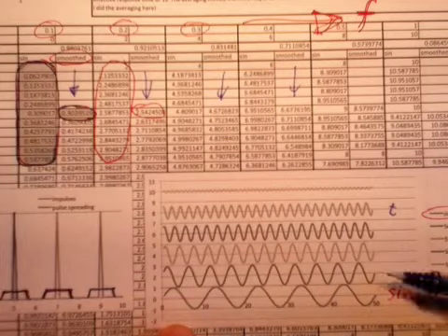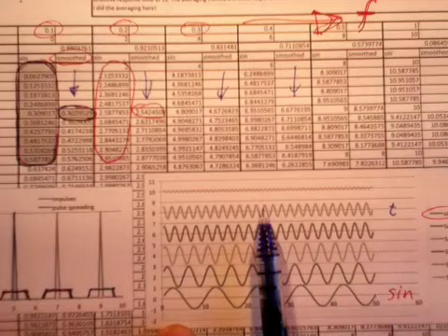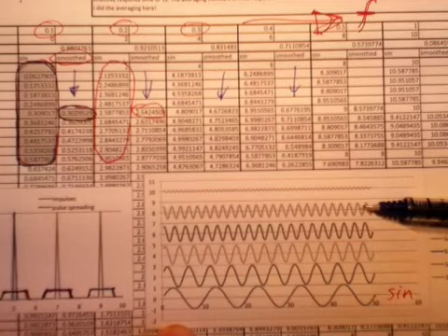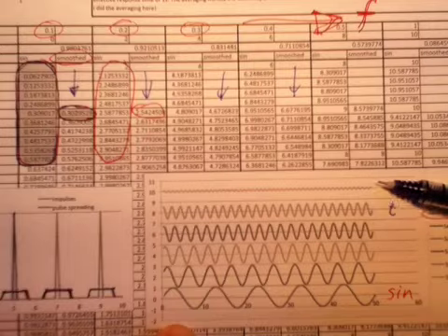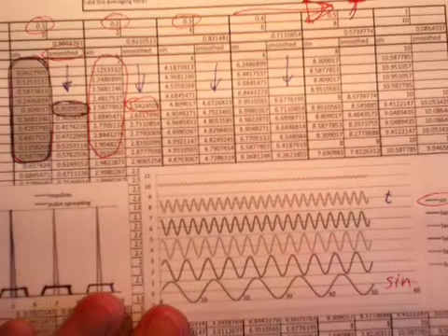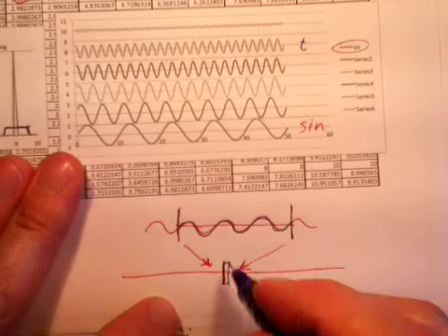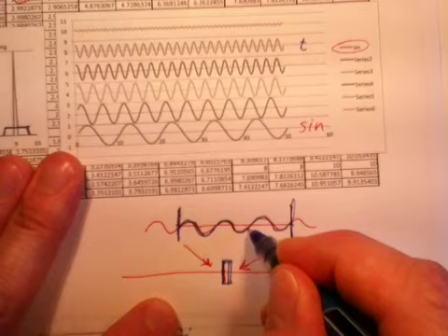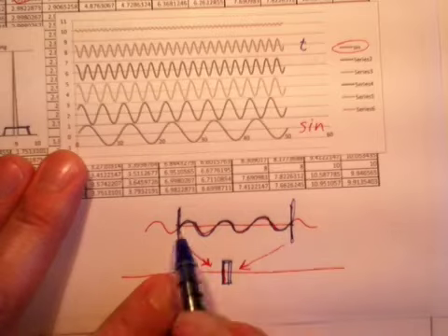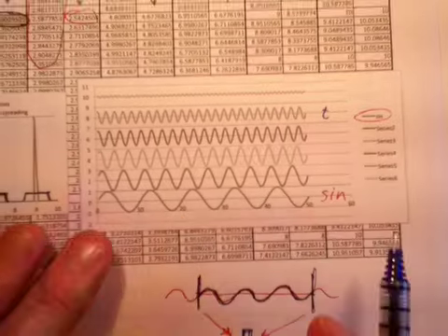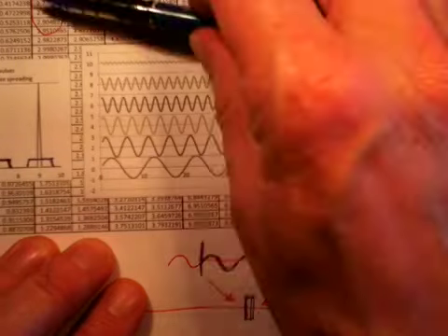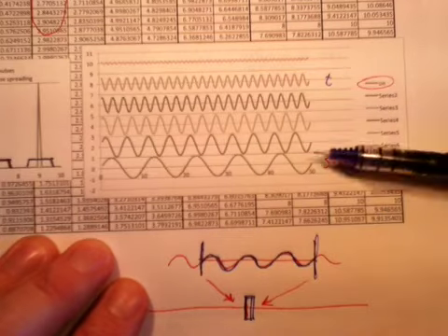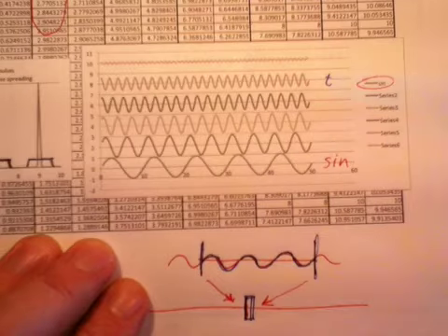Now, as I go to the higher frequencies, you can see as I go up on these different sine plots, I'm going to higher frequencies. But you can also see that the smooth version of the sine waves have decreasing amplitudes as I increase the frequency. And finally, when I pop up to a frequency of 1, the amplitude is very low. Why is that? Because I'm effectively taking this point as the average of points that are averaged over multiple periods of the frequency. When I average over multiple periods, I'm going to get something very close to 0. So this simple model of smoothing out, a pulse spreading type model of the system, really does give us this frequency dependent output amplitude from the system.